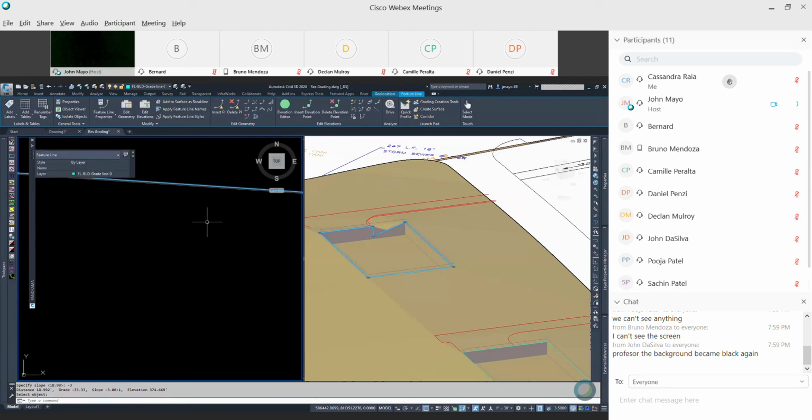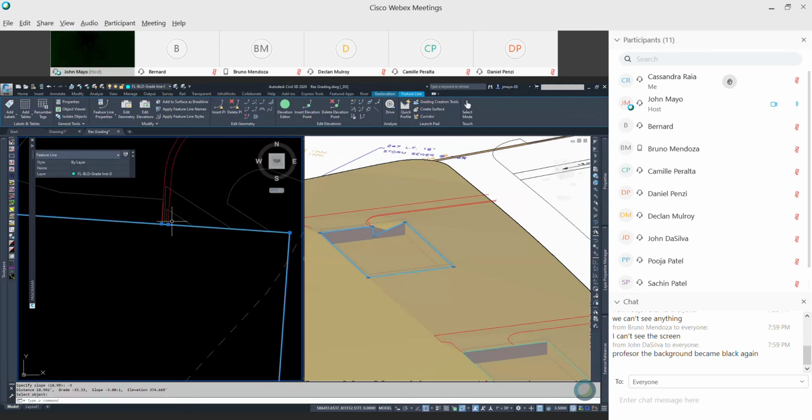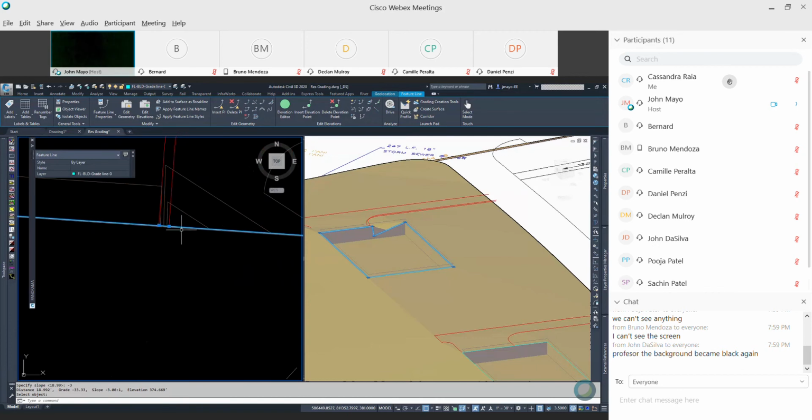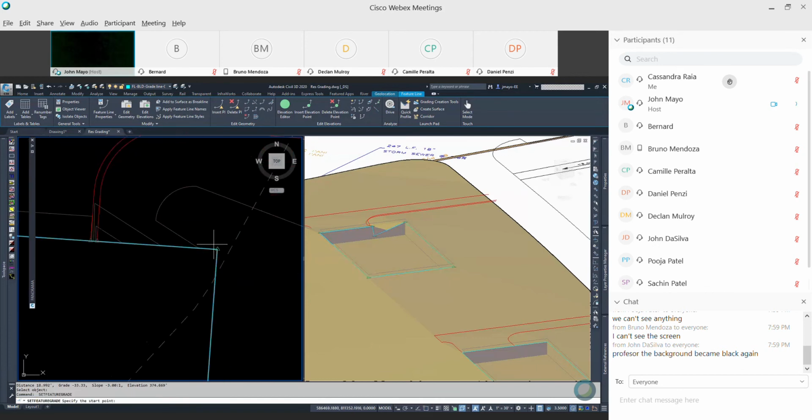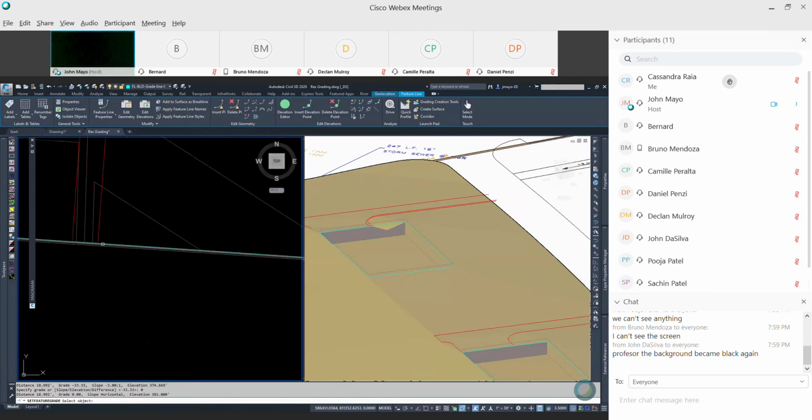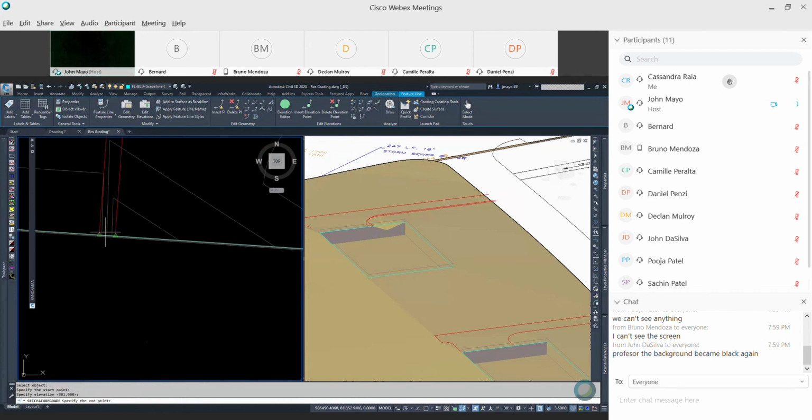And I can check now. Actually, I probably don't want to do it that way. I'm going to do that again, and I'm going to come across at 0 for now. A grade of 0. It brings that back up, and what's my maximum height of wall? 4 feet, right? I'm going to use a grade difference of -4.